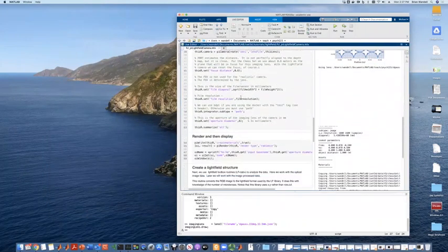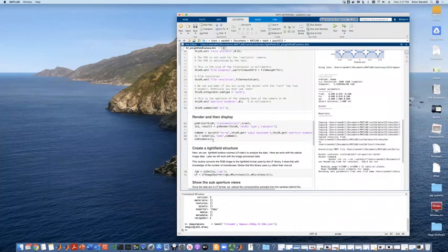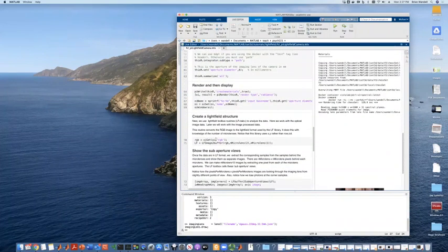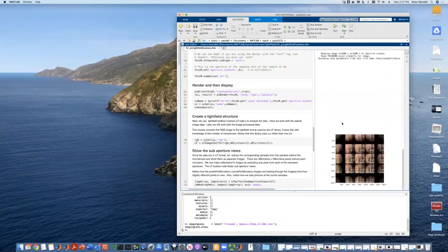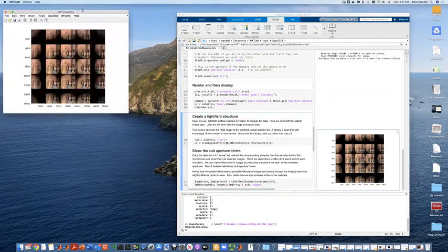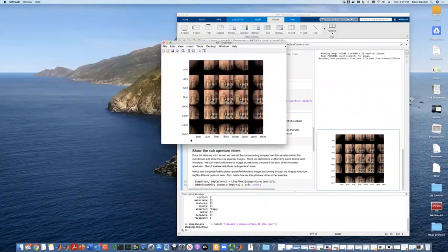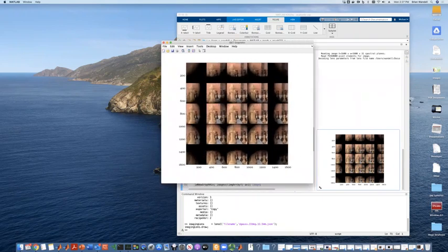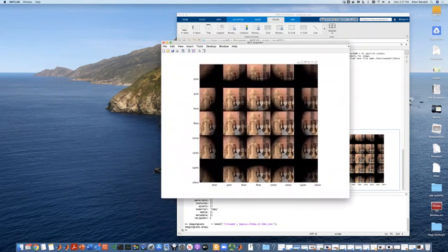Okay. So that provided us with the optical image. And I think it's kind of fun to pull out, even at the optical image stage, the subaperture views. So, we've got 1,600 pixels, but we just rearrange them in this view so that you pull out the pixel at the center of each microlens, and assemble them into a picture. And this picture, ask yourself how big is this picture going to be? How many samples in this picture?